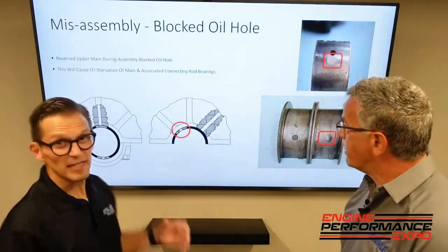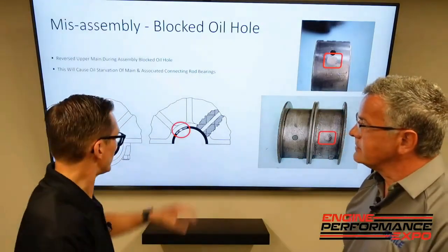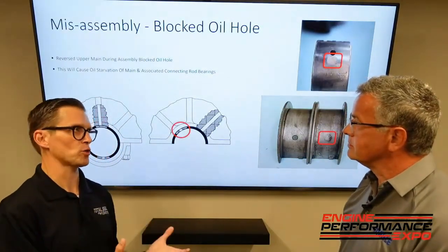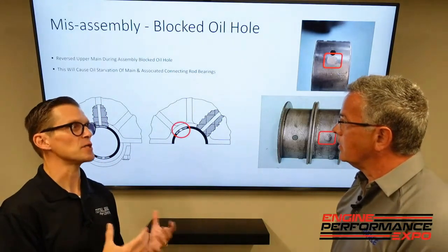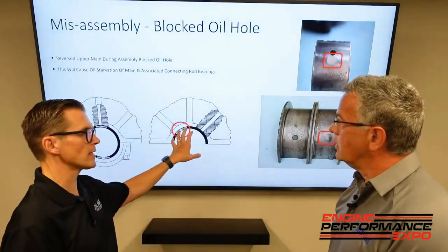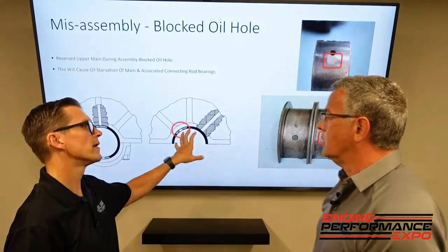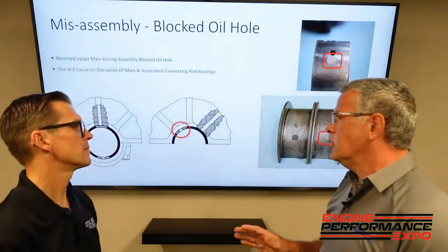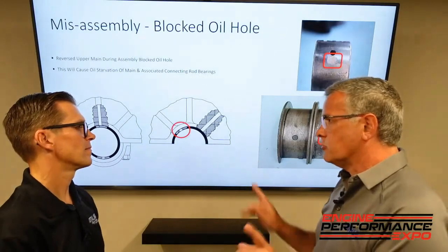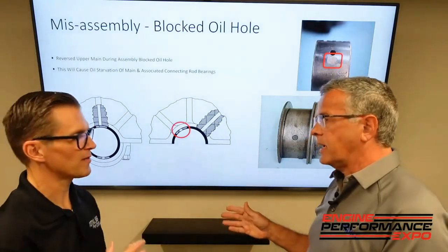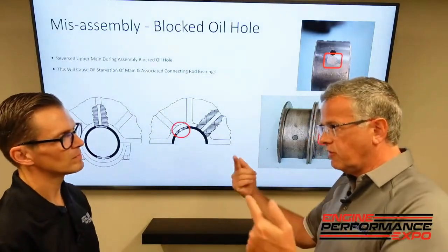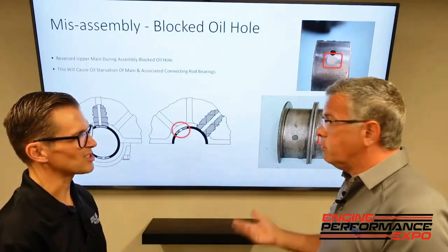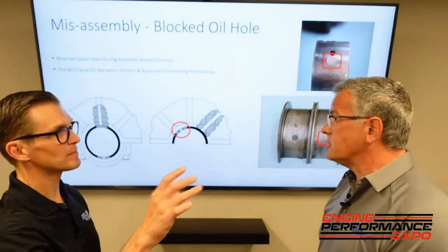Now, I'm speculating here on the fly, but I would think that in this case you would see extremely high oil pressure if you were running the engine, because you're not going to get a lot of oil flow from that point. But maybe I'm wrong. I don't think you would see as much, based off how many rod journals it's feeding. Okay, maybe that's true. Because if you're front to rear and you're only feeding one, it's a lot less. So it may not jump out as obviously.